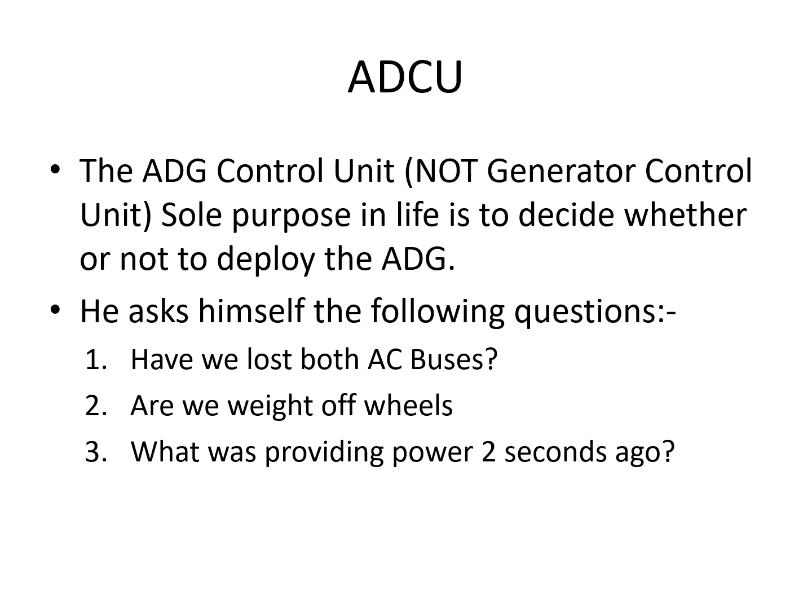So what we have then is an ADCU, the ADG control unit, not to be confused with the generator control unit, which is a separate thing altogether. The generator control unit is looking after the generator side of things, just like any normal GCU. The ADG control unit, his sole job in life is to decide, are we going to deploy this ADG or not? That's his mission.